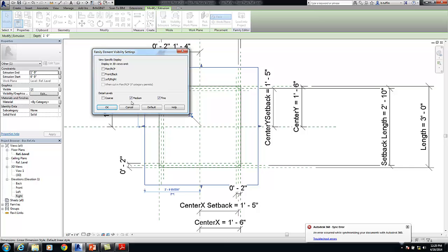If I want to really define something as a fine level of detail, instead of modeling, I'll draw symbolic lines or model lines on a face. Model lines tend to work a lot better. Remember though that anytime you draw a model line, you have to have a reference plane for that line and for each endpoint of that line. So if you're trying to show vents and something, it's going to really add a lot of reference planes inside of there. So let's go ahead and work on this and develop it just a little bit further.